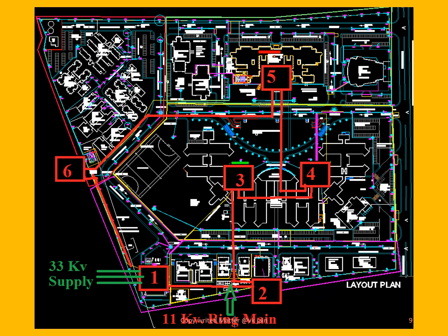They go up to 10% of the entire energy being consumed. So I utilized a concept in which you are getting 33 kV supply because the load was around 10 MVA, and we got 33 kV electric supply from the electricity board and converted it into 11 kV.